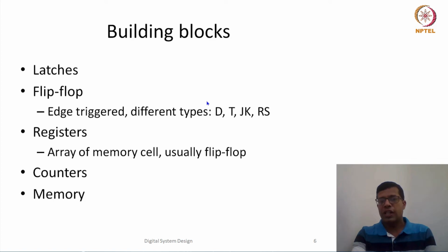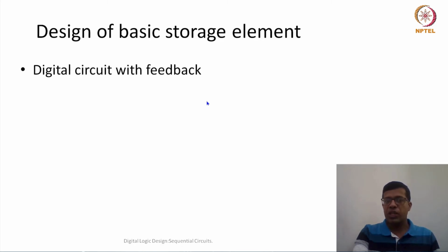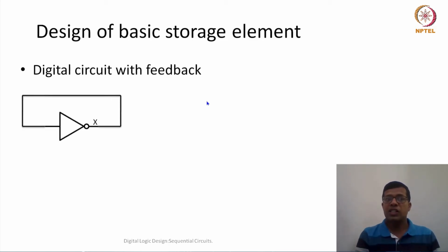So let us start with latches. Latches means we want to design some sort of a basic storage element or a basic memory element. Now, because we want to design a memory element, the basic technique for designing that would be using a feedback loop. In combinational circuits, in our previous modules, whatever we have studied so far, we have never seen a circuit where the output is connected back to the input. What would happen if those outputs are connected back to the input?